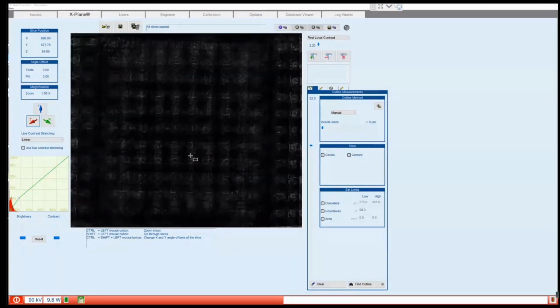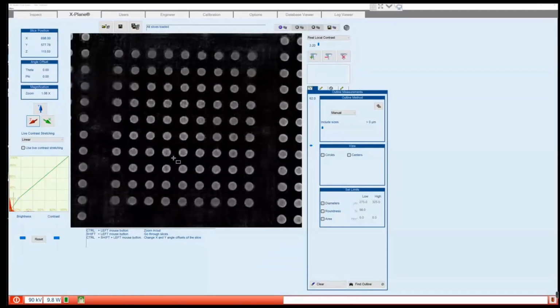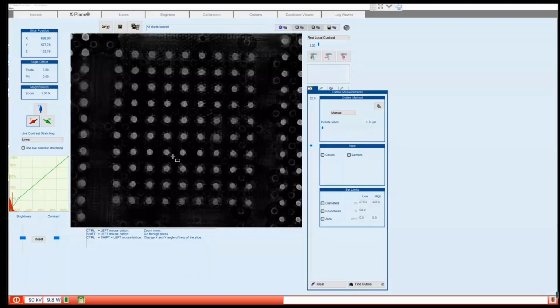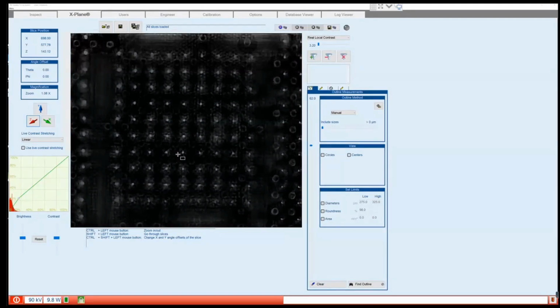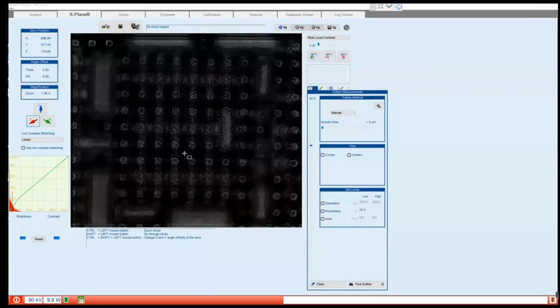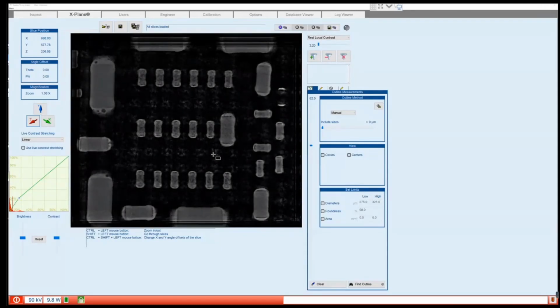Okay, so top of the device, then coming down, we see the solder balls, some voiding, quite small voiding, nothing too concerning. Then the PCB, and then we start to see all these components that were obstructing our BGA device on the other side of the PCB.